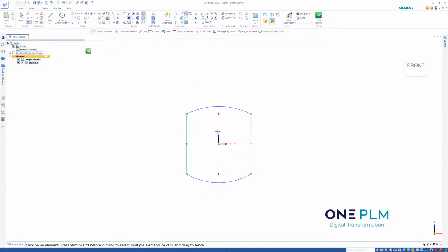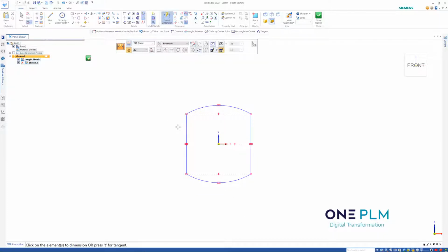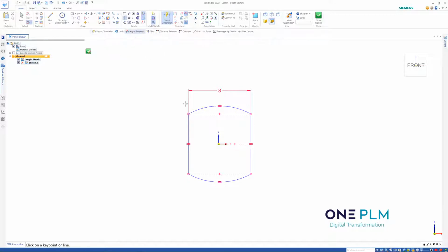I use a couple of equal relationships to make sure we've got equals on those items. We want our width to be that way. Notice I'm doing between two lines, so I'm going to go 8mm on there. Make sure we've got the appropriate relationships in, so it looks as though I haven't got a connector there because it was connected to the horizontal.